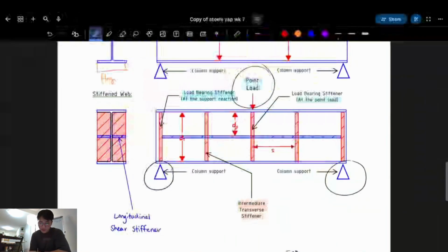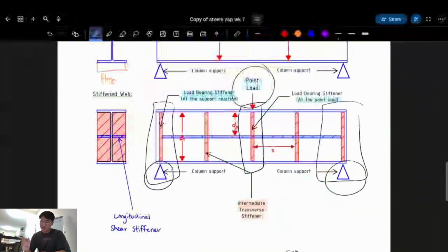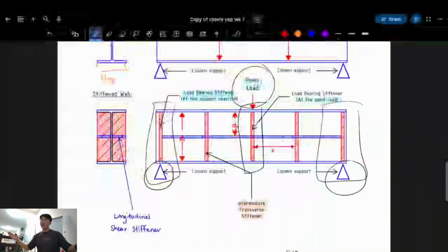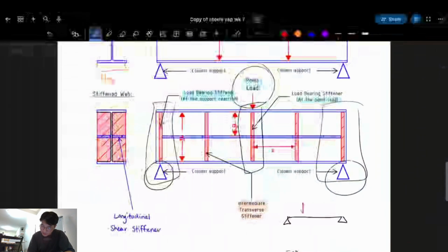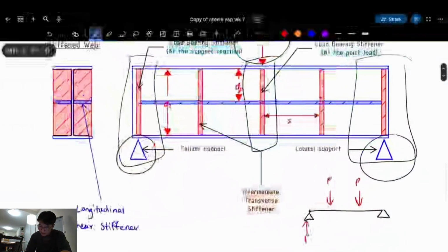And so if you're going to put in stiffeners at the point load, you should consider putting them where there are reactions as well. In this case, we've got one point load and two reactions, and it's even, right? So how much of the point load is each reaction taking? Half, right? Okay, say we had two point loads, and this is still even. How much is each reaction taking? Half of the total. So now this is matching.